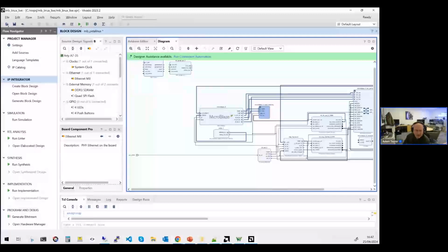I'll run through this again, Brian, because I'm curious about that question as well. I think the main thing is, when you first do the block automation, the only thing you've got is to be able to select either bare metal, real time, or an application processor. And I think that's the reason why I selected it, not the Linux MMU. But we'll double check that in a few minutes at the end of this session. So we've added in the AXI timer.